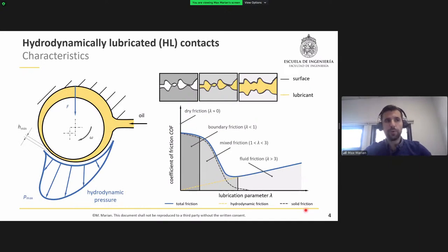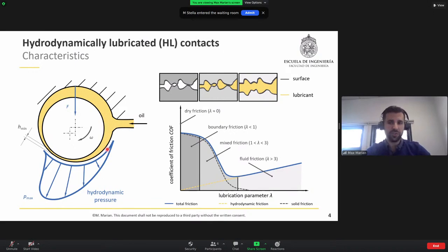The use of lubricant, of course, is an effective way, both in nature and in industrial technology, to reduce friction and wear in highly stressed tribological contacts due to the partial or complete separation of the contacting partners by an intermediate medium, the lubricant, which generally has a lower shear resistance. The formation of a separating hydrodynamic fluid film depends on the gap geometry, the relative movement of the contacting surfaces, the viscosity of the lubricant, and also the adhesion conditions.